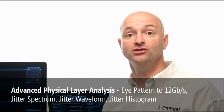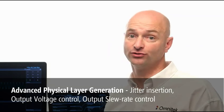So to wrap up, the Advanced Physical Layer package contains a lot of tools for both analysis and generation to enable design engineers and system installation engineers to debug and design 6 and 12 gigahertz systems. And these go well beyond traditional waveform monitors. And so on the analysis side, again, we have 12 gigahertz eye pattern, jitter meters, jitter spectrum, jitter histogram, and jitter waveform. And then on the generation side, we have output jitter insertion, output voltage control, and output slew rate control.